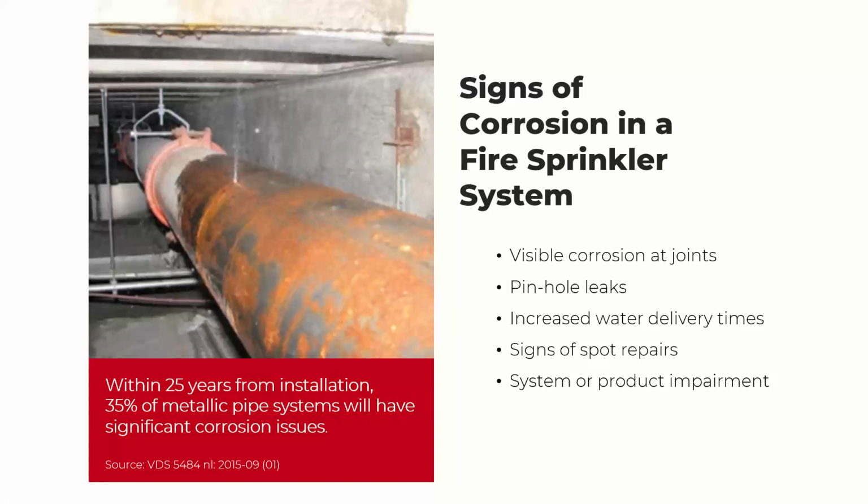It has been a rule of thumb in the fire sprinkler industry that system designs were in 50-year increments. But we're discovering that through a variety of causes, it could be thinner wall pipe, or it could be, and that's one of the bigger issues, system design and layout, that we're not seeing nearly the anticipated longevity in systems, and corrosion is having a big impact on that.